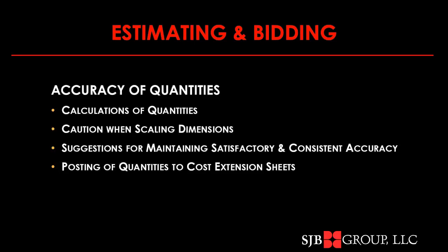It's seldom necessary to be more accurate in your dimensions than 1/8 inch. And you can also remember that 1/8 inch is approximately 0.01 of a foot. So if you can get those conversions done as you're writing numbers down initially, the whole process will go quicker. When you're doing mass earth calculations, 1/10 of a foot may be close enough, especially if the final grading is specified to be within 1/10 of a foot accuracy.